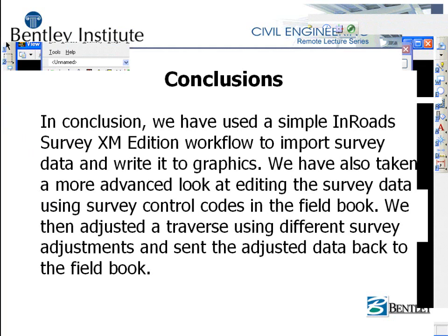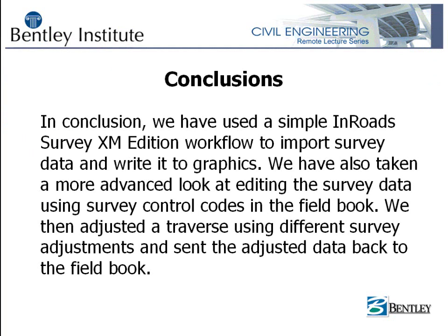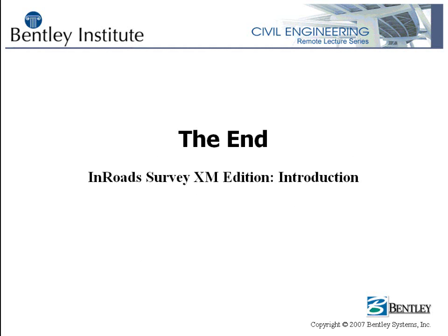In conclusion, we have used a simple InRoads Survey XM Edition workflow to import survey data and then write the different survey data to graphics. We have also taken a more advanced look at editing the survey data using survey control codes in the fieldbook. We then adjusted a traverse using different survey adjustments and sent the adjusted data back to the fieldbook. This concludes the presentation for InRoads Survey XM Edition introduction.